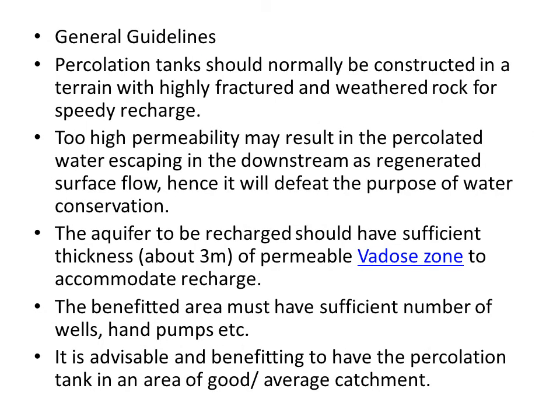The general guidelines in the design are: a percolation tank should normally be constructed in a terrain with highly fractured and weathered rock for speedy recharge. Too high permeability may result in the percolated water escaping downstream as a regenerated surface flow, hence it will defeat the purpose of water conservation.